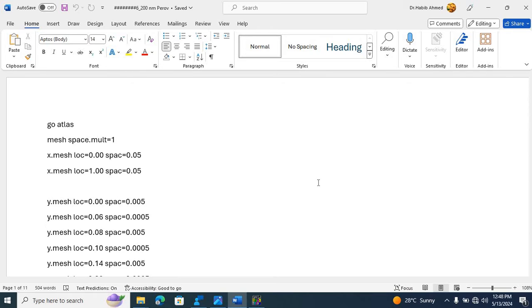Secondly, perovskites have high electron and hole mobility, so their diffusion lengths are larger, which means that when you generate electron and hole pairs inside the perovskite solar cell, they are not going to be recombined right away. They can travel to the anode and cathode contacts, get collected at the opposite electrodes, resulting in contribution to current and voltage.